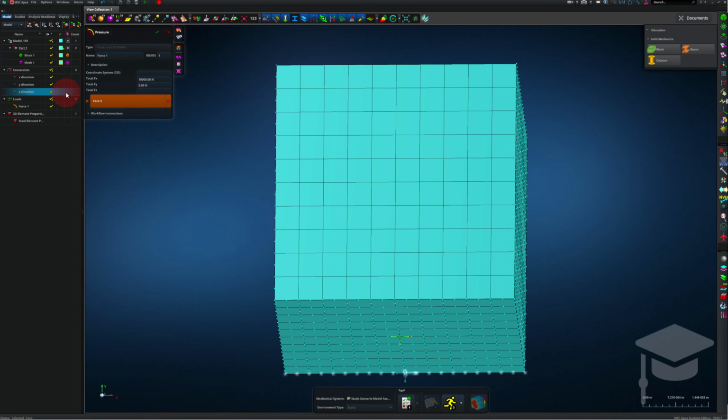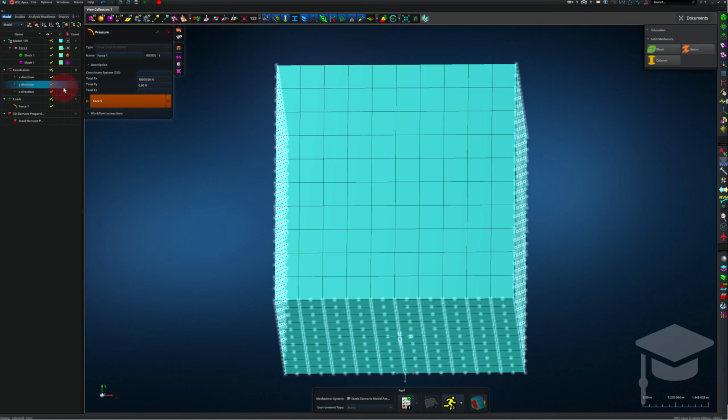It is also not very important because we don't have any force in the z direction. The y direction constraint is kind of funny, so let me try to explain this one to you. We constrain not just the bottom like we do for normal, but we also constrain the left and right hand sides. If we did not constrain those, the block would actually be under a combination of this pure shear load and a bending load. So that winds up giving you a non-uniform stress profile.